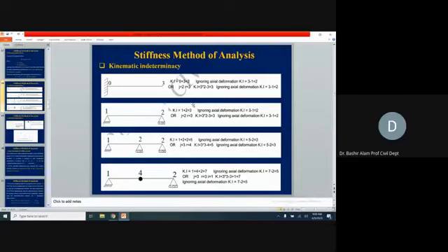Now, if we go by the equation, how can we do it? We have two joints, so j is equal to 2. Number of reactions: at the fixed support we have 3 reactions, so r is equal to 3. What was the basic equation? There is no hinge. So it means 3j, 3 times 2, minus r, so minus 3, is equal to 3.